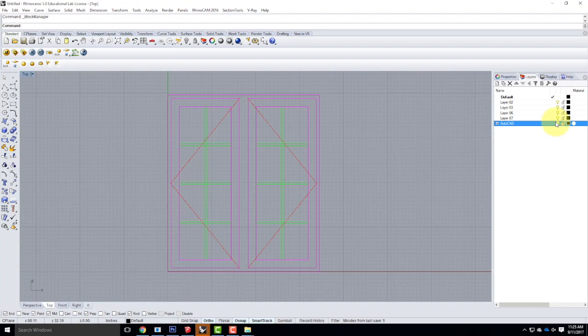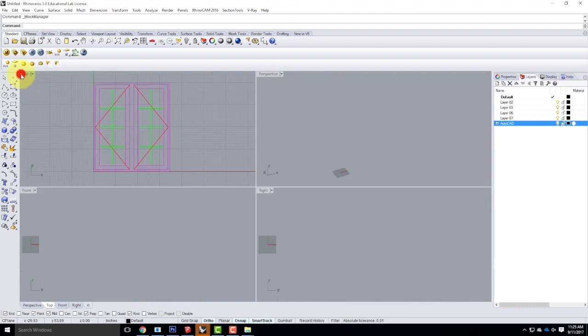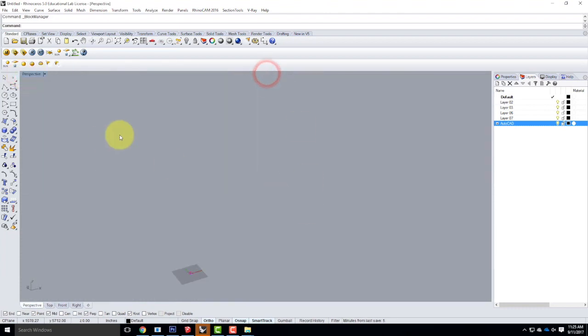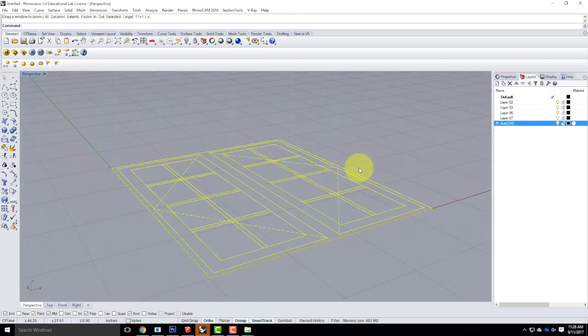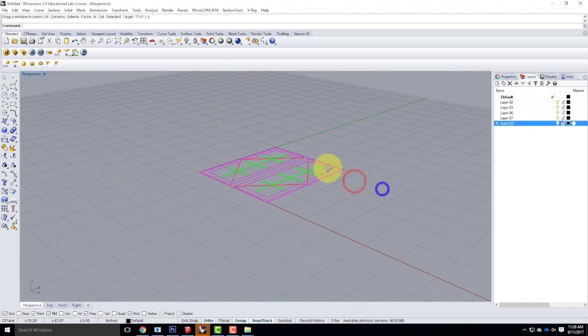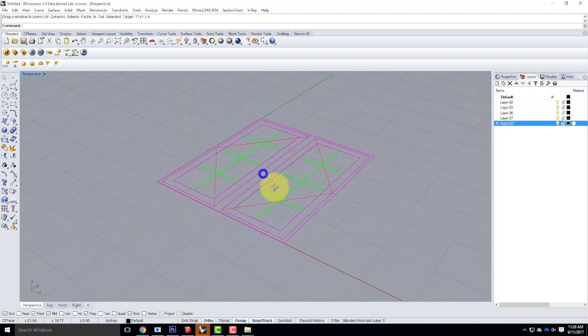So now I have to start thinking about how exactly I am going to model this, and what it's going to look like. Well, first off, I have to start creating surfaces, because right now, this is just a series of lines. Let me switch over into the top view. Let me zoom selected here, Z followed by S. So this is just a series of lines. So I have to start, number one, dividing it up and starting to see how I could maybe extrude these. And I think extrude is probably the easiest strategy for creating the initial depth.